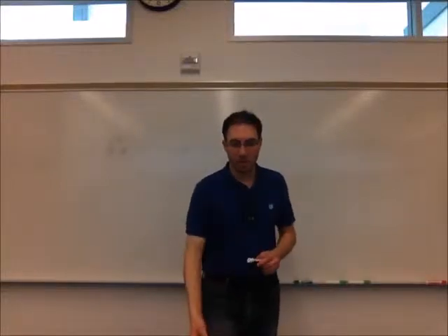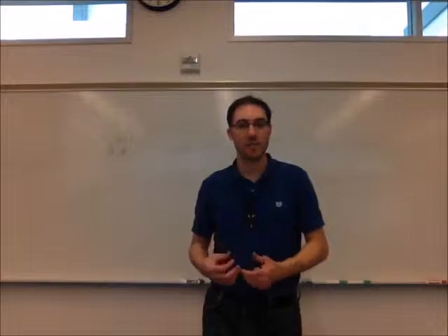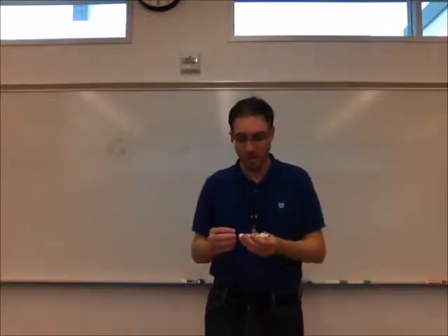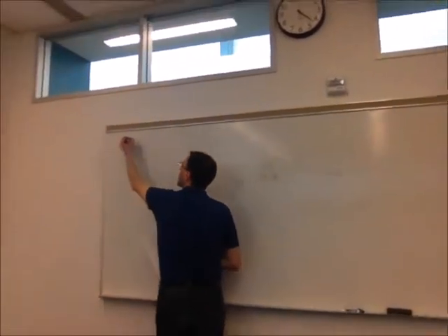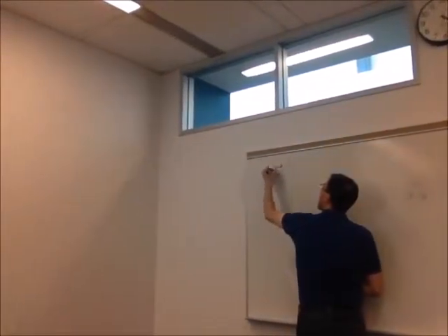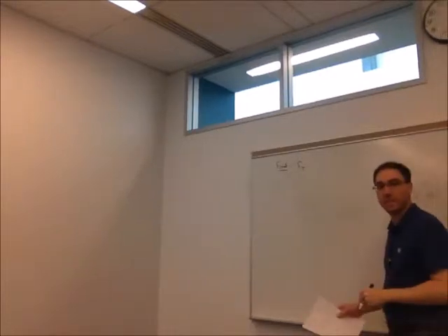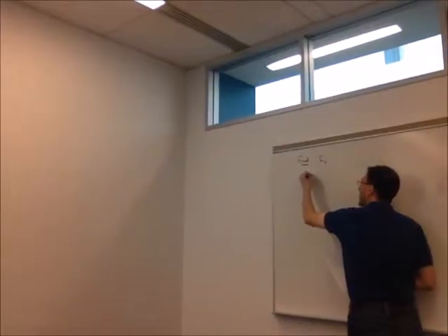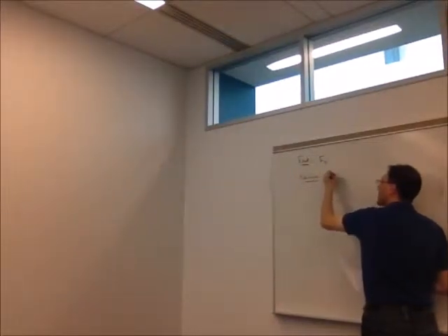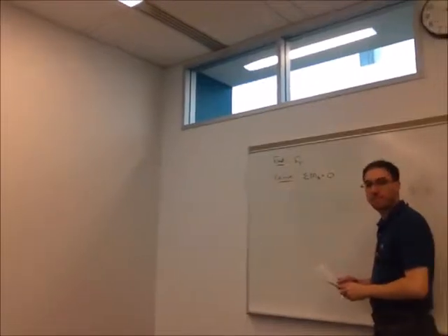In this biomechanics problem, we're trying to find how much force the muscle or the tendon has to exert to keep this ankle in equilibrium under these conditions. So, what we're trying to find is that force F sub t. And what we're given in this case is that the problem is in equilibrium, in that the sum of moments around point A is going to be 0.